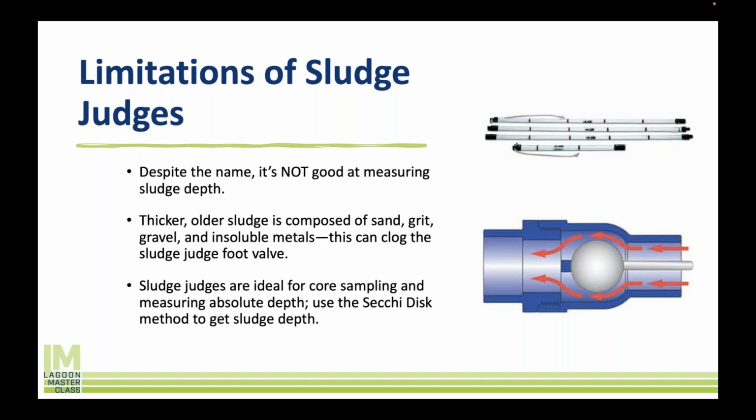What they're really ideal for is total depth measurement, right? So how deep is my lagoon from the bottom to the top? And not all lagoons are flat, by the way. So every time you do a measurement for sludge, you want to figure out what the total depth is at that point. The second thing they're really good for is pulling that all-important core sample. They will allow you to get a decent enough profile of that core of the sludge in order to send it to a lab and get the testing done that you need to get done.